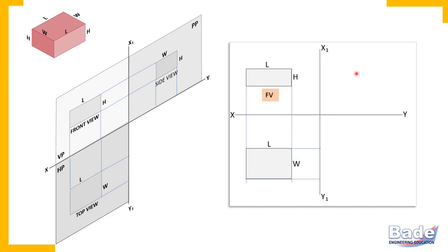Okay. Now to draw the side view of the object. Which two dimensions do we get in the side view? Width horizontally and height vertically. So height is vertical in the side view also. Transfer it by drawing horizontal projectors. This is how we have drawn end projectors. These are called end projectors from front view to side view. These are horizontal lines perpendicular to the X1, Y1 line. So this is how you have transferred height in the side view.